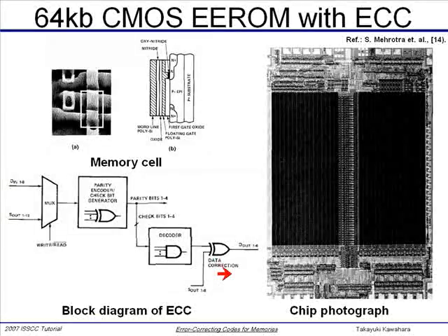The purpose of the ECC is reliability. The ROM has a very thin oxide, and for hot carrier or tunneling they program through the electrode. So the information is deteriorated by leakage of the oxide or such a thing. Therefore, they need the ECC.